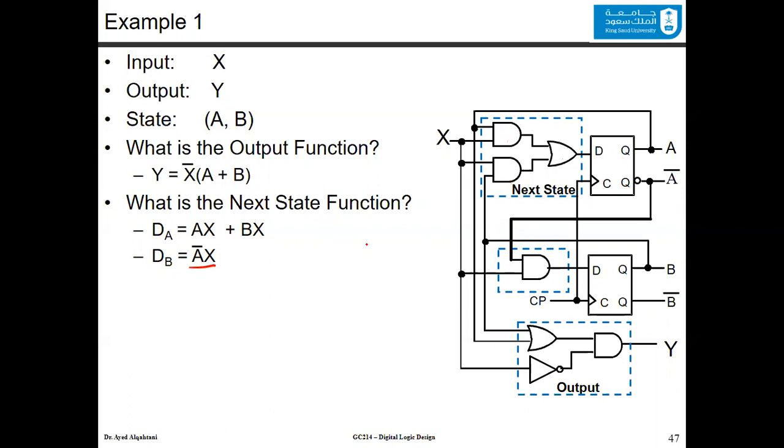Now this is one of the good points about the D flip-flop or even D latches. You have Q, both Q and Q bar. So whenever you want A, you can get it right away. Whenever you want the complement of A, you already have it in the Q bar here. So the output of every flip-flop is generated in its normal form and in its complement form. As you can see, we generated the equations fairly easily from the block diagram. So we were able to analyze this block diagram and generate its mathematical model, being the Boolean functions.